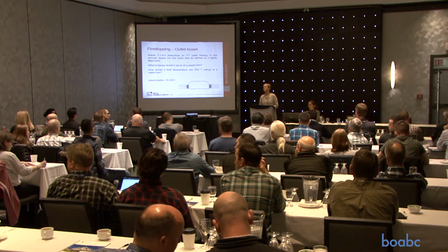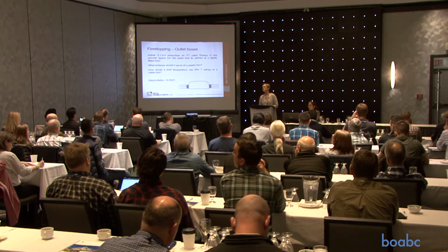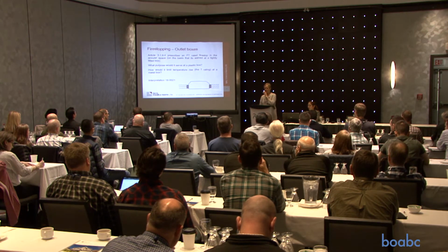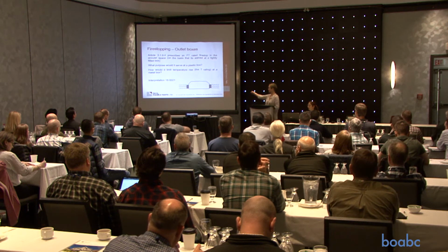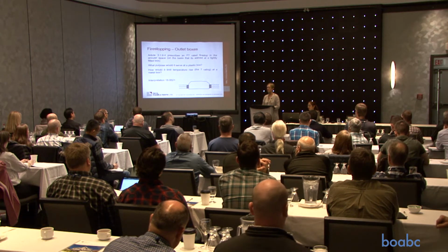I don't know. Anyway, I believe this is on the province's radar, and they're going to maybe get it. I think it's also on the national code people's radar that there's some issues with this section. Has anybody attempted to address that by putting a layer on the outlet boxes? It says you have to limit the T rating. How do we do that? Well, it seems to say you have to do it in the annular space. Doesn't seem to say that you have to do it behind the outlet box. It's a bit silly, really.